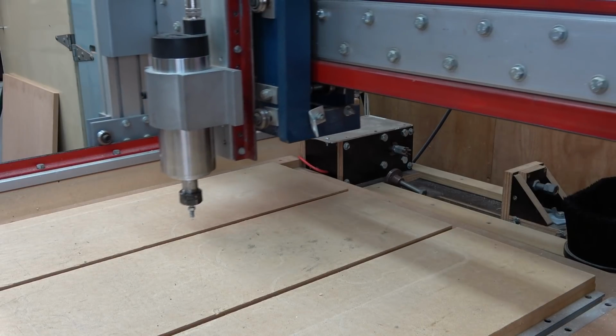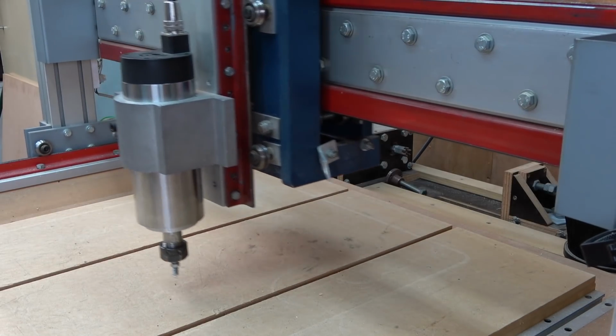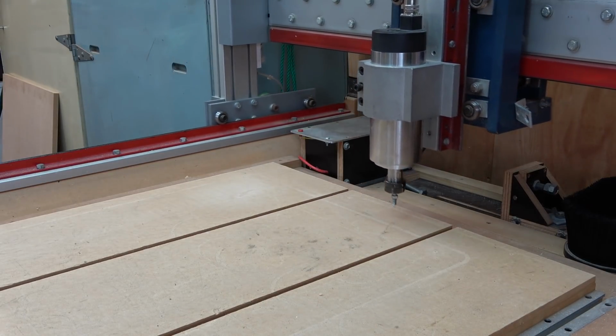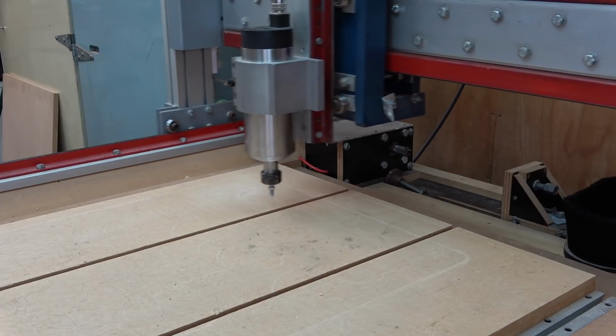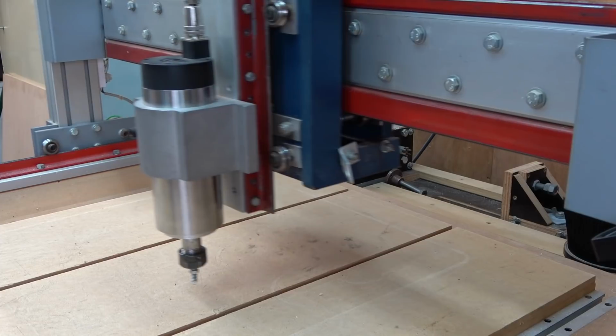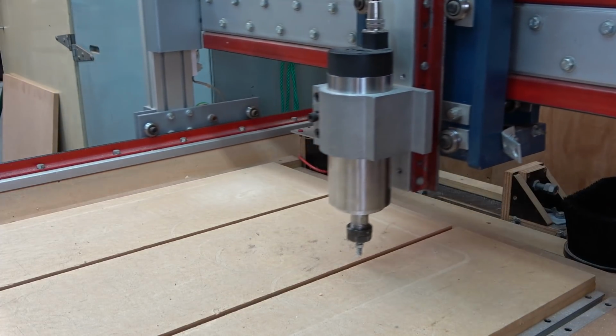So this first demonstration is using the Masso CNC controller running in exact stop mode. And as you can see, it's running smoothly around the oval shape until it gets to here where it stops, drops the cutter further into the material and continues running around. Now I'm using this to demonstrate that not all exact stop motion control is the same. Machines that specialize in exact stop motion have far superior motion control than those that don't.